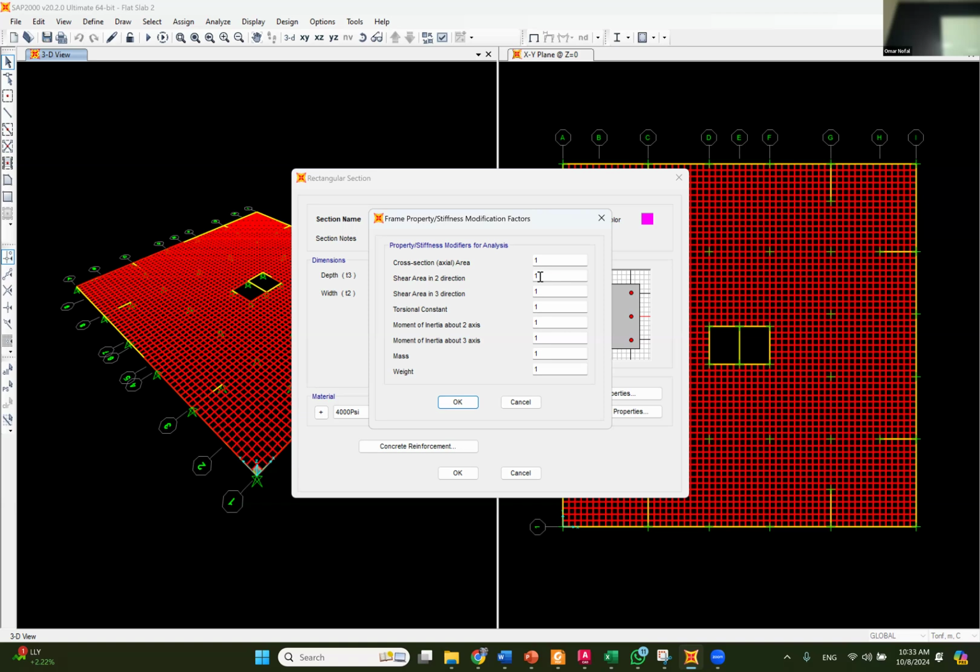So that means you have a section 25 by 70 multiplied by 10, the inertia multiplied by 10, okay? Or you make hinges here. And you can delete this section. Both of them are the same thing. All right, so right now we are done with our model. Let's assume that we have done this, or we are accepting the 0.5 millimeter deformation.